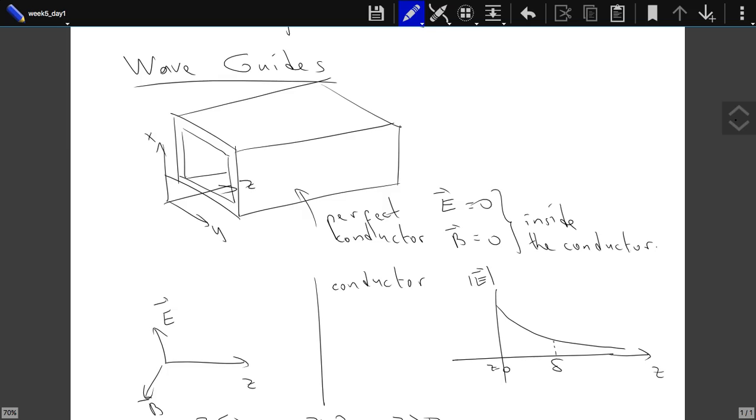Well, it's important in the sense that for such rectangular cross sections, we are able to solve it in class. For another shape, I mean, you can put arbitrary shapes you want. It doesn't have to be rectangular. But rectangular shapes are easy to construct for practical reasons, and they are easy to study analytically. As we will see, we will be able to solve this problem analytically. This one, and also the coaxial waveguide, 2 cylinders. An arbitrary shape, well, you need to use computers.